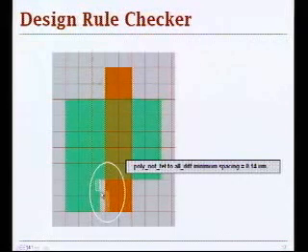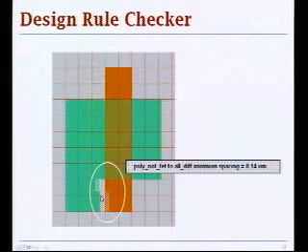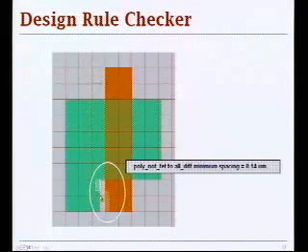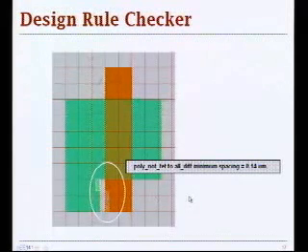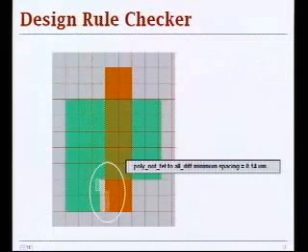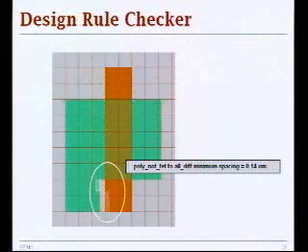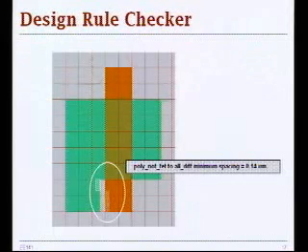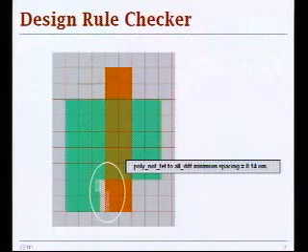So it's basically when you have a violation, you will get a warning that there is not sufficient spacing, in this example between poly and active area. What's also important is that most of these design rule check engines implement so-called hierarchical design rule check, because for the complexity of designs that we talked about last week, you have millions and millions of transistors, but luckily they are hierarchical in a sense that you repeat one cell all over the place a number of times.